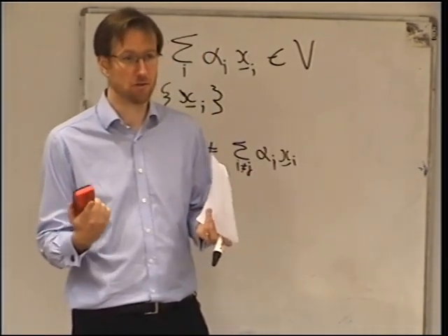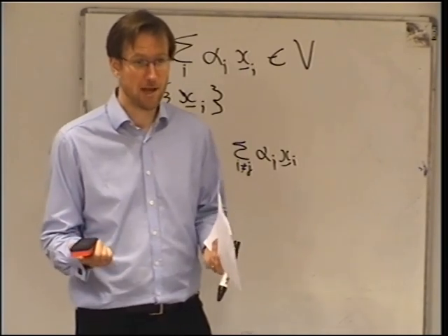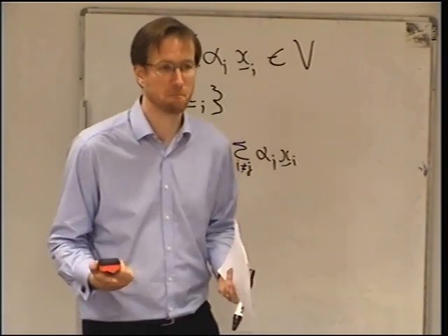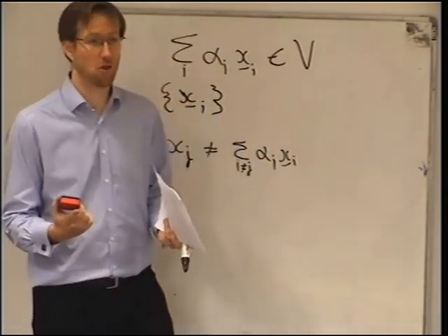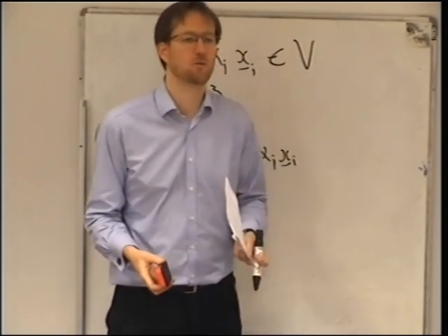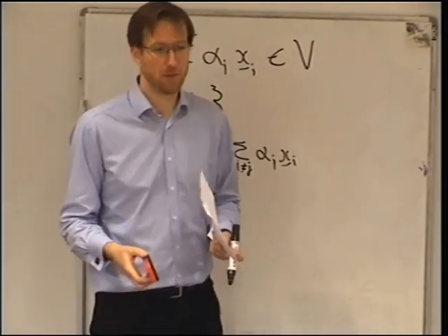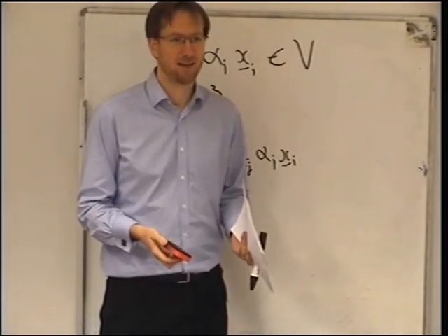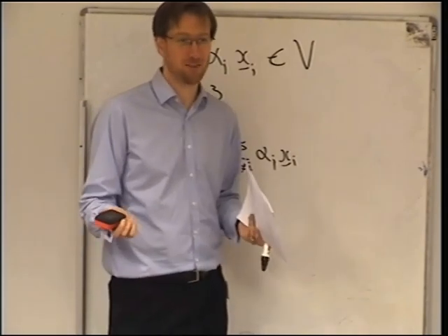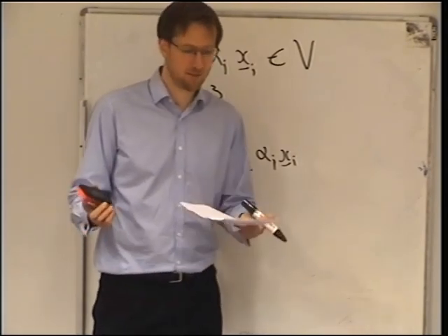So you need an infinite number of basis functions to describe all the vectors on there, and that's seriously inconvenient if you, like me, have a finite-sized computer. And so the whole story about what we're going to do with the finite element method is we're going to attempt to solve the problem in the right subspace and choose a subspace which is finite dimensional so that we can fit it in the computer.